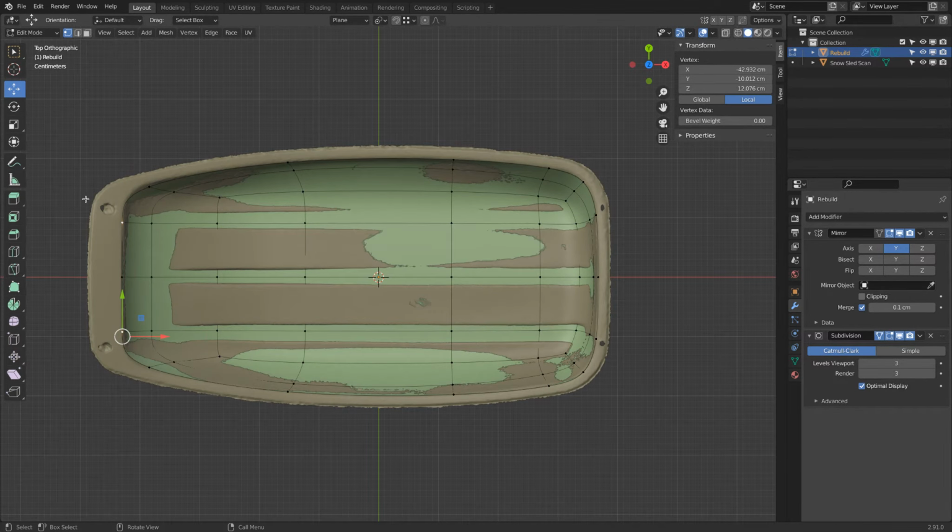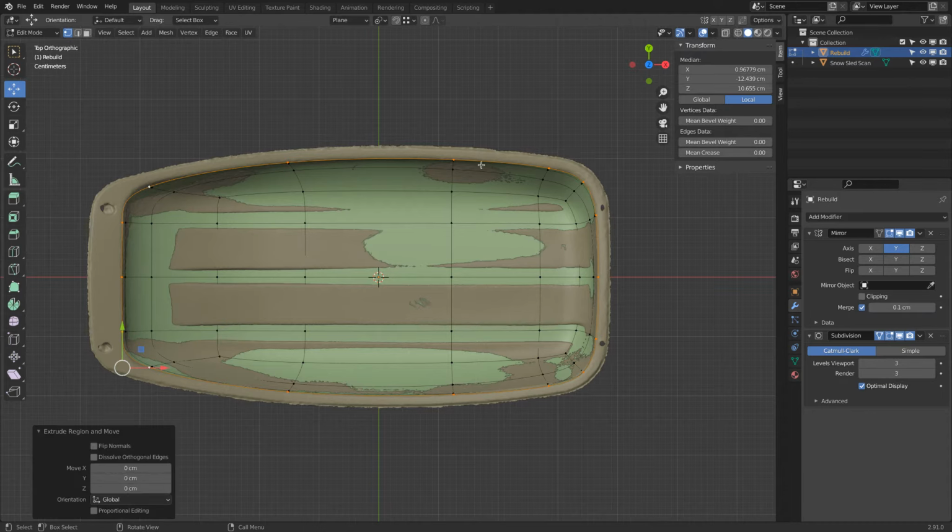So how do we model this rim? There are two ways to do this actually. I could select this via Alt click on this upper edge, which selects the whole loop. Then I press E for extrude and escape. And let's go to bounding box. Actually here we'll go to 3D cursor, so it's right here. This is perfect.